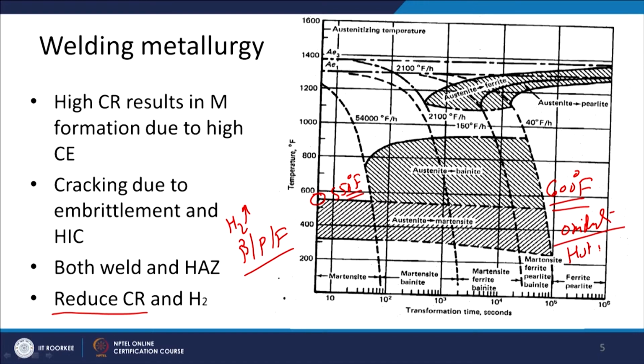So, working with the hot plates during the welding as well as oxidation tendency, these are the two adverse effects which are associated with the higher degree of preheat. Although it will help in reducing the cooling rate, and it will also help in reducing the hydrogen content as well as the formation of the martensite, the cracking tendency will be reduced, but it will make the welding difficult due to dealing with the hot plates as well as due to the formation of oxides by the steel plates when they are heated to the high temperature during the welding.